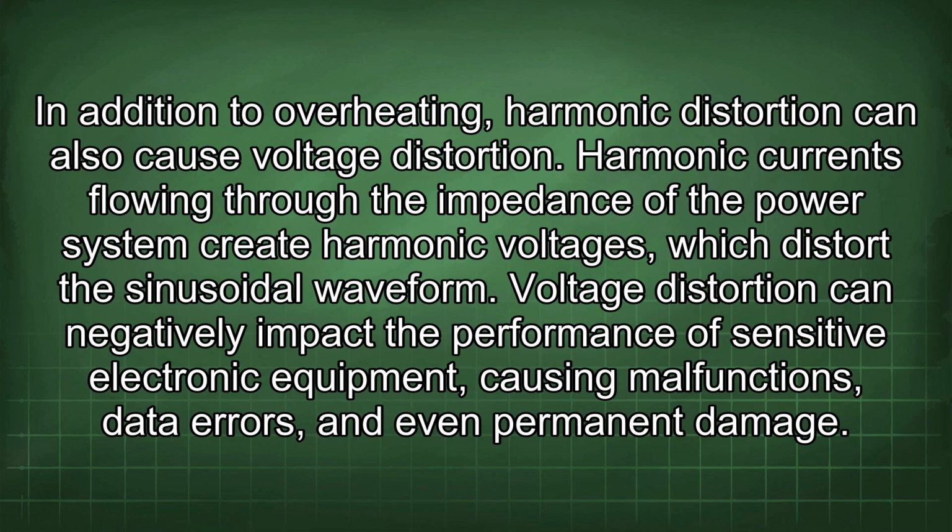Harmonic currents flowing through the impedance of the power system create harmonic voltages, which distort the sinusoidal waveform. Voltage distortion can negatively impact the performance of sensitive electronic equipment, causing malfunctions, data errors, and even permanent damage.